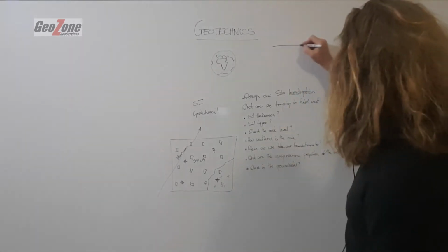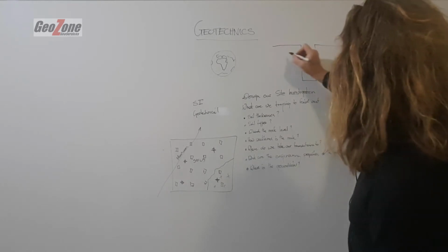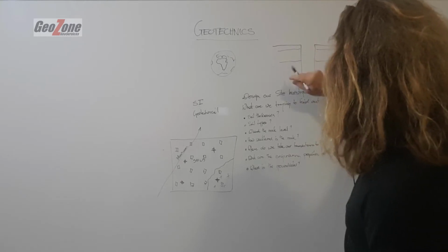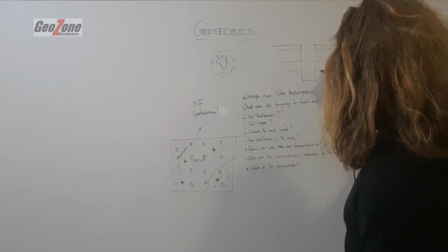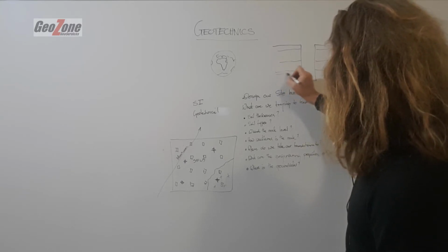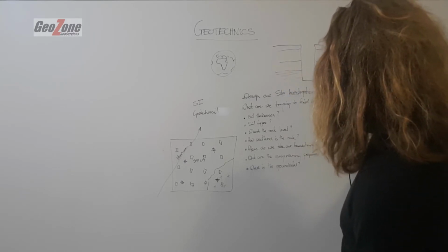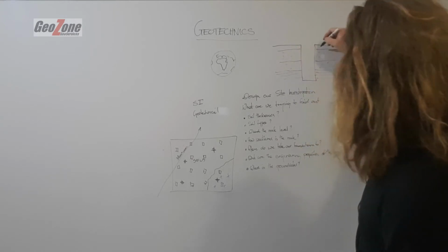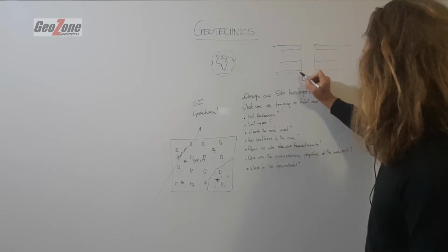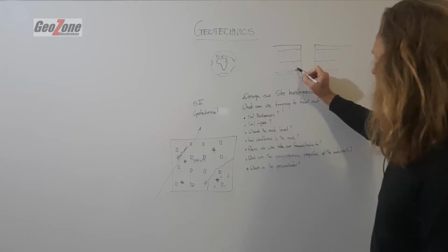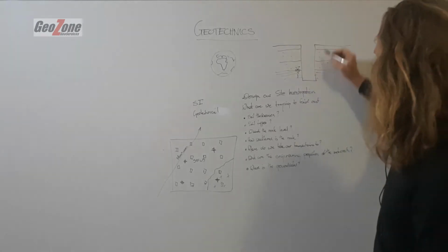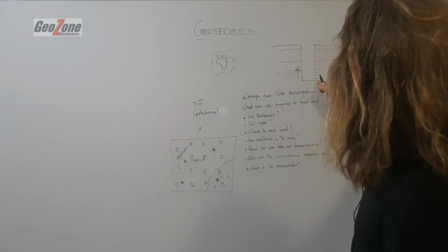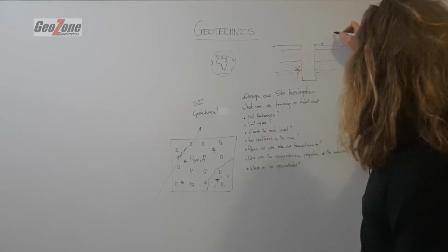So a test pit. We dig a test pit, and we've got colluvium, and we've got residual soils. Residual. And then we get another layer of residual, and then we get the bedrock, the highly weathered shale, or whatever it happens to be. Colluvium. Hey, the water might be sitting somewhere here at the interface. I'm just speculating here. Yeah, we understand where the water is. We dig a pit, there's refusal. We know that there's a decent founding horizon down here. That's ground level, of course. We're standing here.